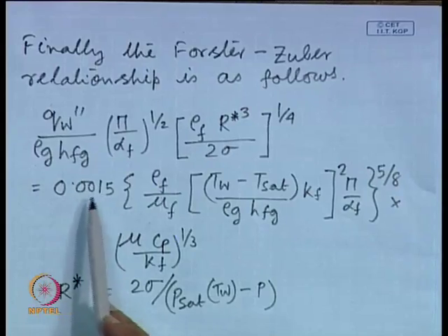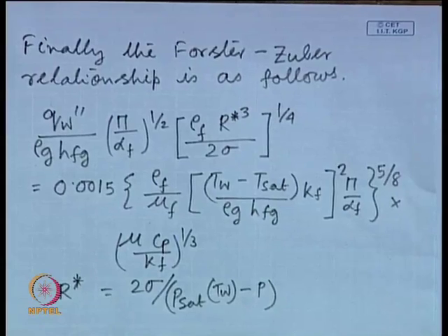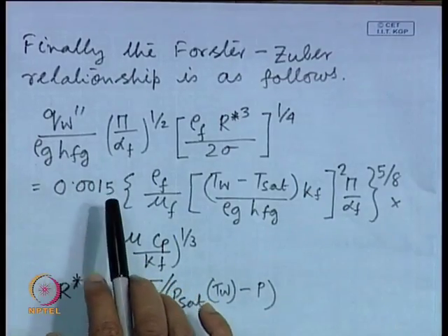But again CSF has got some sort of a physical meaning, that it is dependent on the solid liquid combination. It takes care of the wetting property of the solid, like your contact angle. It takes care of the activated nucleation sites on the solid surface, but in this case it does not have any sort of physical meaning.